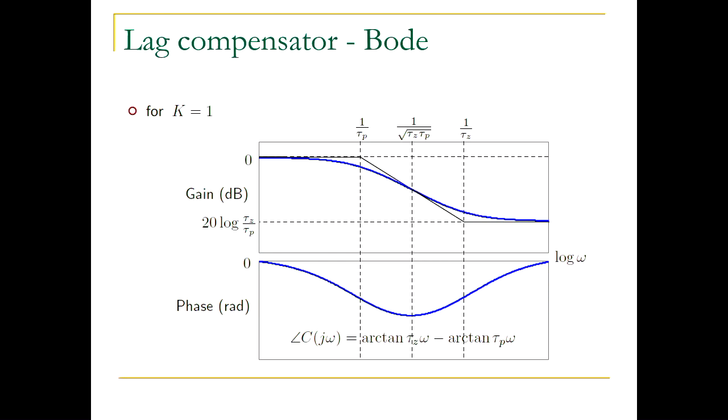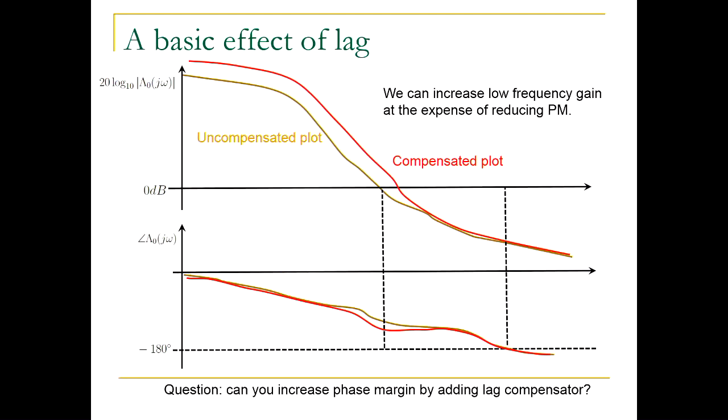So, all right. Now, how can this be used in compensating the loop? So here is one picture. Now, this example is qualitative. It's not supposed to give you exact numbers. We will do a lot of computations for specific examples later on. This just illustrates what's possible. So the brown line, brown Bode diagram, I said it's the uncompensated plot. That's actually the plant's Bode diagram. So the plant's Bode diagrams are brown and they are uncompensated Bode plots.